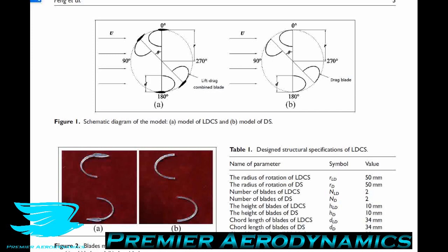Then once the blades have rotated more, the pitching angle drops enough for the airfoils to start producing lift again. So once it gets to maybe about here, again it's backwards, but the airfoil still produces some amount of lift. This approach, as I mentioned, is quite new. So that is what we're looking at in this podcast right now.